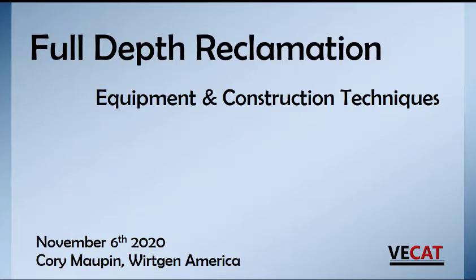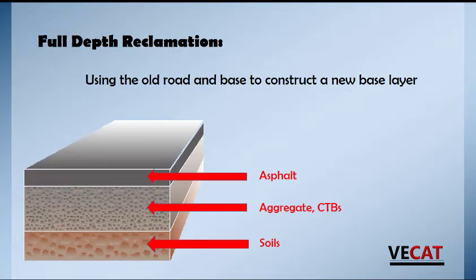Today we're going to be talking about reclamation or full depth reclamation. In full depth reclamation, we're taking an asphalt layer and mixing it into the aggregate layer below it and trying not to get into any of the cement or the soils beneath. We'll talk about that more in the next slides.